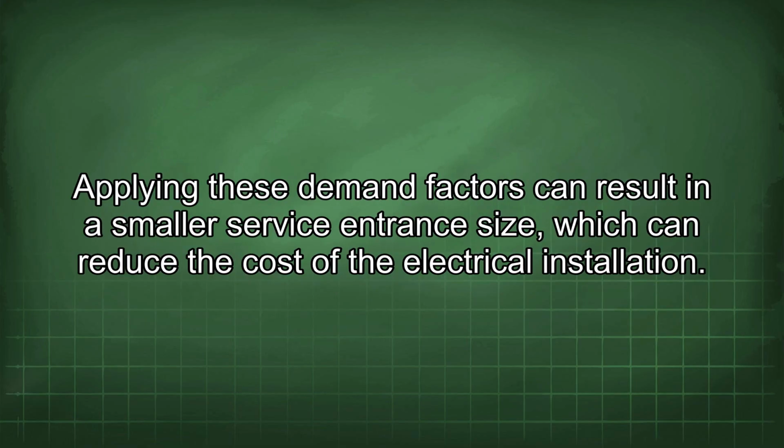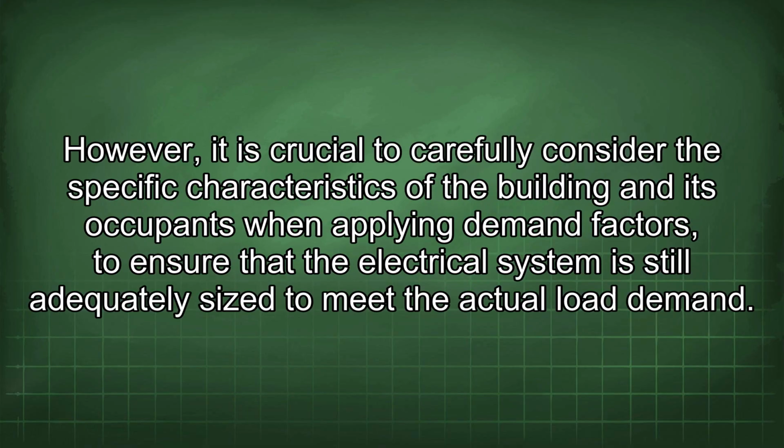Applying these demand factors can result in a smaller service entrance size, which can reduce the cost of the electrical installation. However, it is crucial to carefully consider the specific characteristics of the building and its occupants when applying demand factors to ensure that the electrical system is still adequately sized to meet the actual load demand.